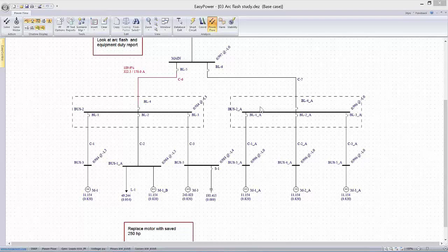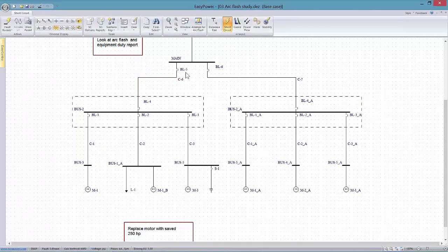All right, so in the world of power systems design, duty refers to how close to the maximum rating a particular device is being used. And particularly in protective devices or bus systems, the duty refers to the maximum interrupt current that it's guaranteed to perform at.